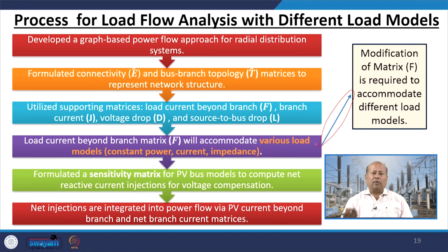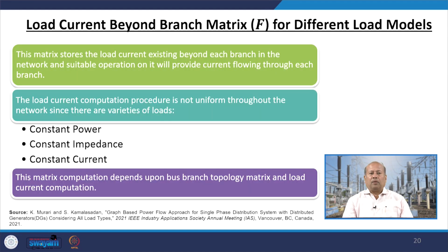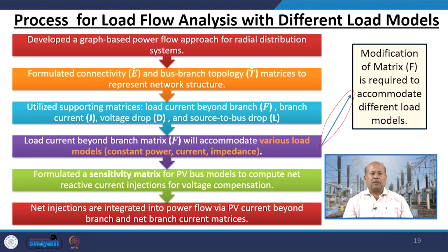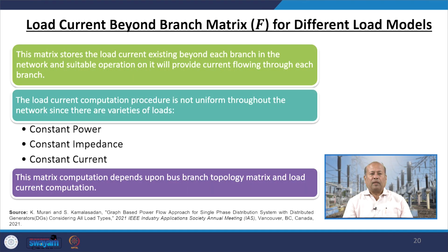So we need to modify depending upon different load conditions, but at least we'll start with a couple of different load models in our discussions. Majorly we'll focus on constant power, constant impedance, and constant current, but if you go beyond, you have to readjust your F for different loading conditions.